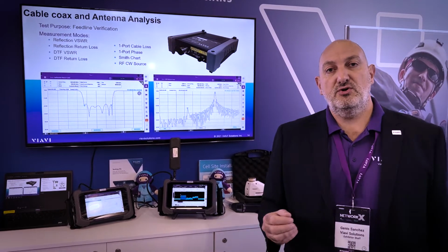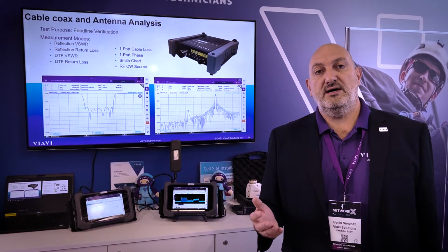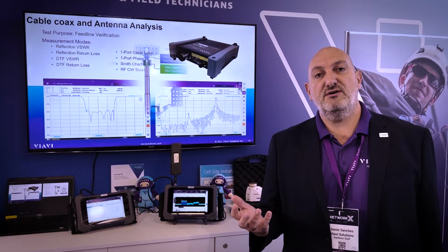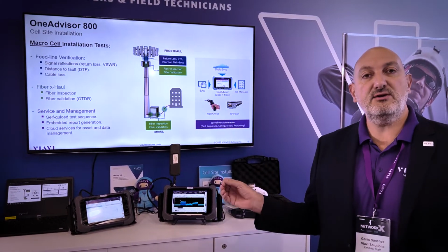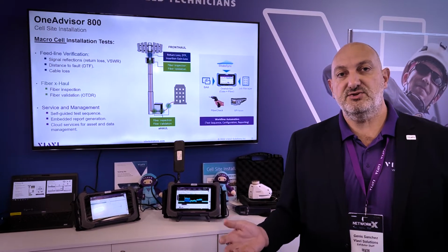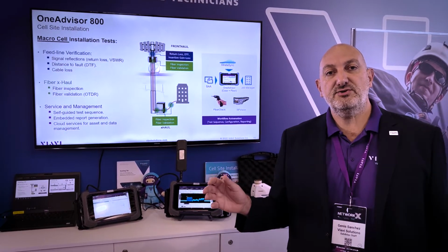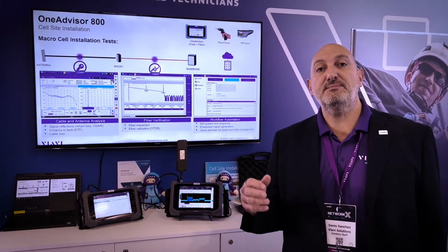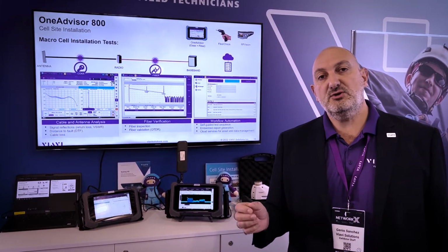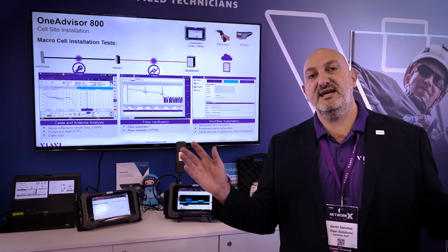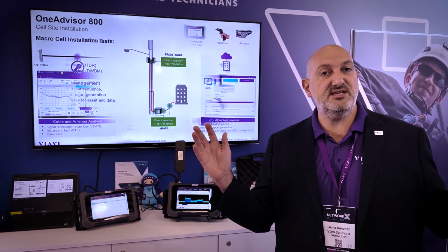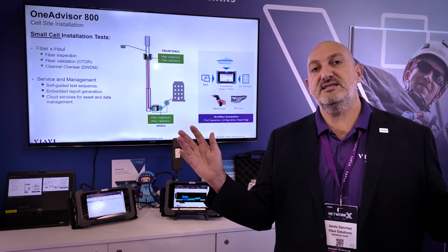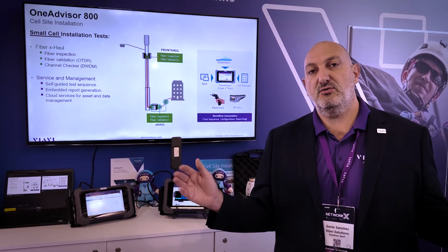Finally, also on the 5G side, we are able to do deep analysis and troubleshooting of how good or how bad you are broadcasting 5G from those base stations, including 5G over-the-air synchronization. This is the ability that we have to measure that all the signals radiating from all the sectors are correctly synchronized in absolute terms against a GPS reference, but also in relative terms between the different sectors. So we can tell you if two adjacent, neighboring sectors are correctly synchronized as per the 3GPP recommendations.